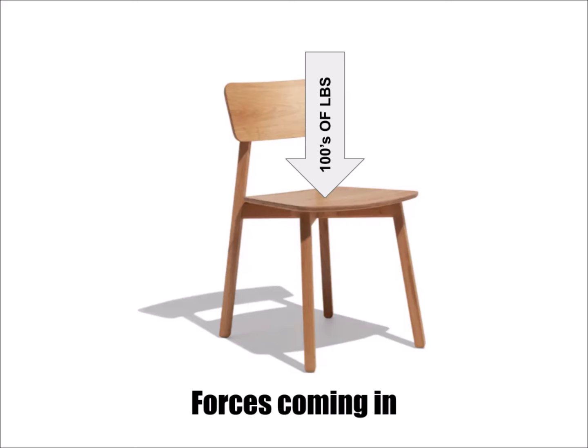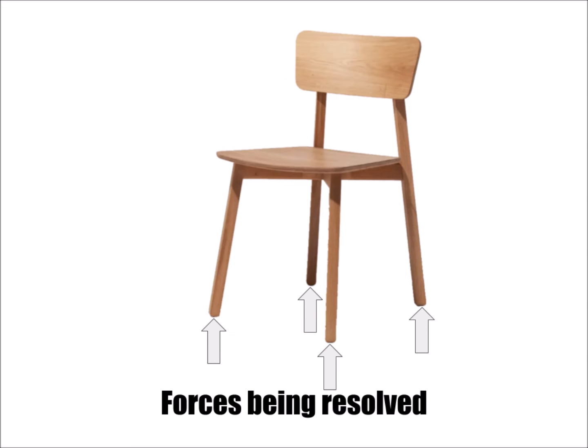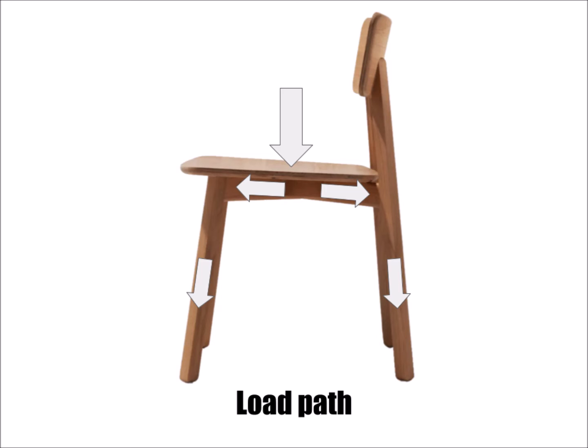First, what are the loads and how are they applied? Here, it's hundreds of pounds, straight down. Second, where is the force resolved? In this case, reaction forces from the floor do the job, with roughly equal forces on each leg. Finally, what path does the load take from where it is applied to where it's resolved?